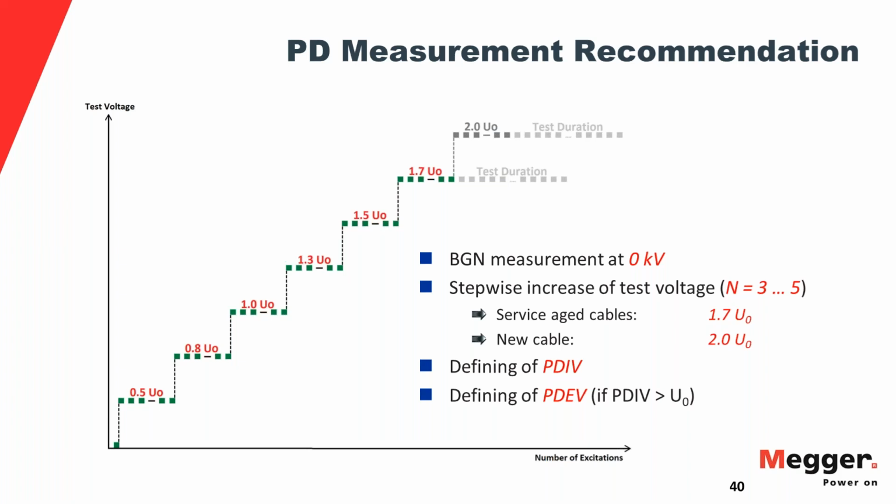And that is pretty much your minimum threshold, or your floor that you cannot go below. If you have a condition that is below the background noise, no chance of finding that in the field. That's the nature of field testing. You have background noise, and then you start at a certain voltage and increase it in steps, not too many measurements, not too few.